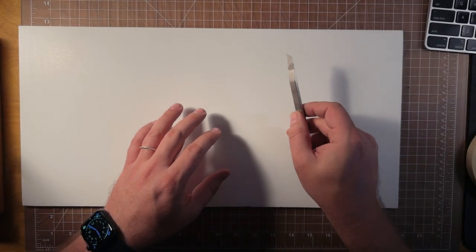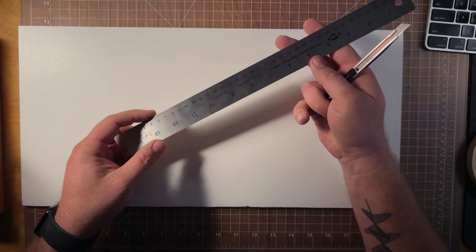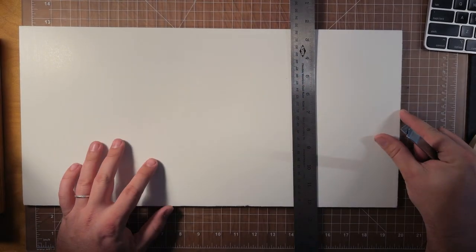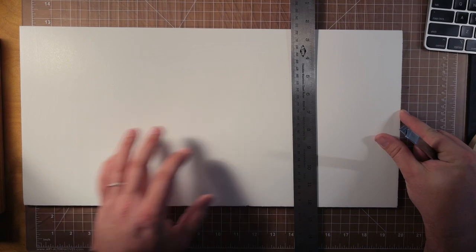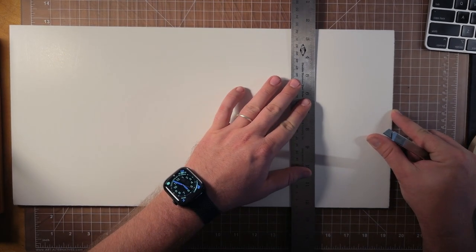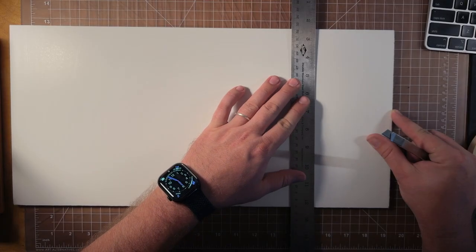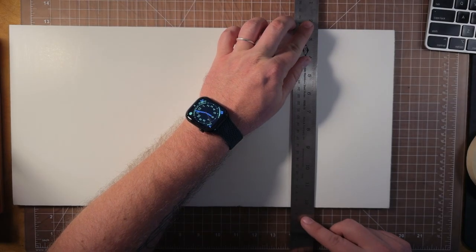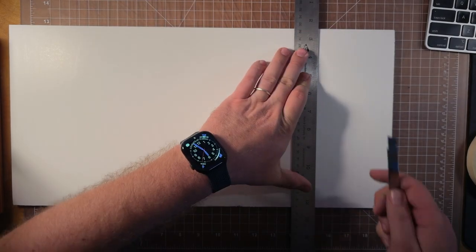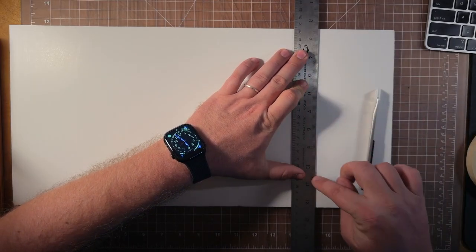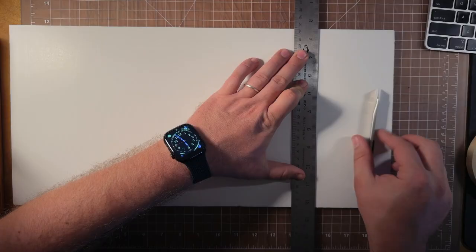The idea that we're pressing lightly with the blade is very important, so I'm going to demonstrate a kind of cut. I'm using a metal ruler with a cork back so that it won't slip. And with my pre-cut piece here, I'm just going to cut, let's say a 4-inch piece. So at 15 inches should give me 4 inches. Using my cutting mat in the background, which is important to have a nice cutting mat, I'm going to lightly score this material for the first pass. I'm going to hold the ruler so that my fingers are not too close to the edge of the ruler, but where I can put firm pressure down on the ruler.